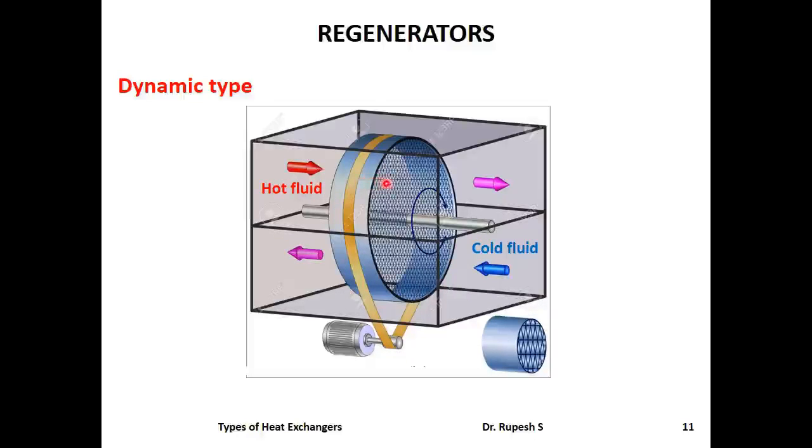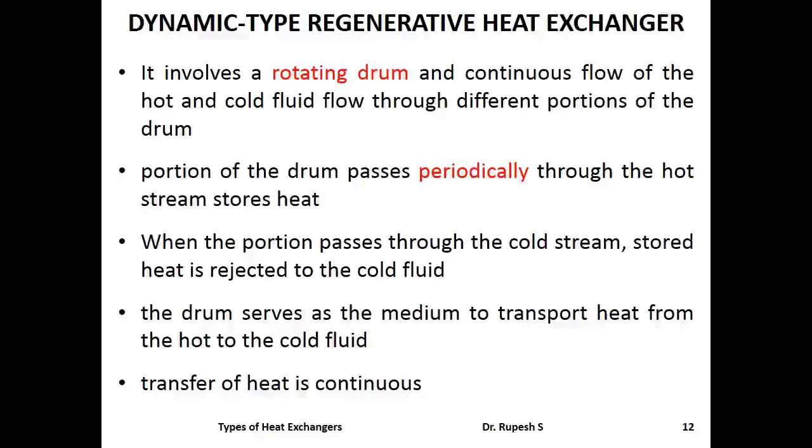Heat stored in the drum when hot fluid flows during one half revolution is transferred to the cold fluid in the next half revolution due to the rotation of the drum. Here, in a dynamic regenerator, heat transfer is continuous. These are the points pertaining to the dynamic type regenerative heat exchanger.